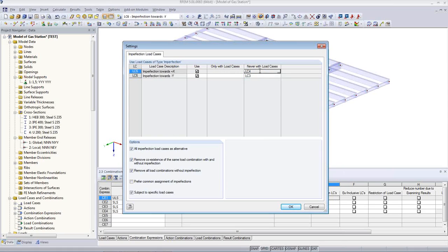If I use common sense, I can figure out which load cases or load case combinations are most likely the ones that control, and I don't have to analyze an immense amount of combinations. If you don't want to use it, you can forget about it and just do all combinations, but it will result in longer calculation time and more data to analyze and so on.